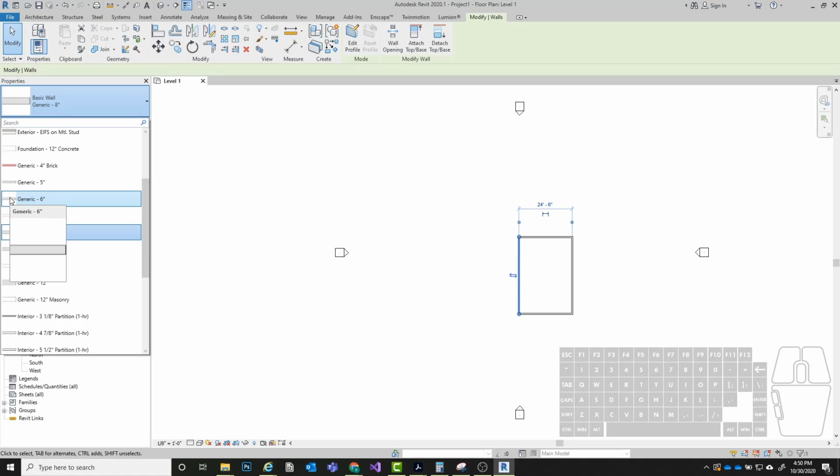By layer information, I'm talking about what kind of stud is inside of the wall, what kind of sheathing does the wall use, is there a sheathing on the exterior, does it have gypsum wallboard, okay, so like drywall. Does it have layers of drywall? And if so, how thick are those layers? Are they a 1/2 inch thick? Are they 5/8 of an inch thick? All of that stuff is important, and we can build that level of detail into our Revit model.